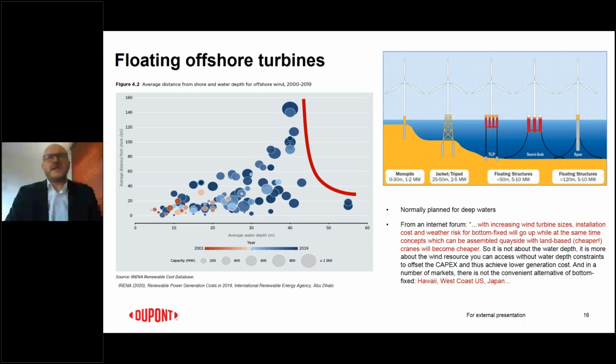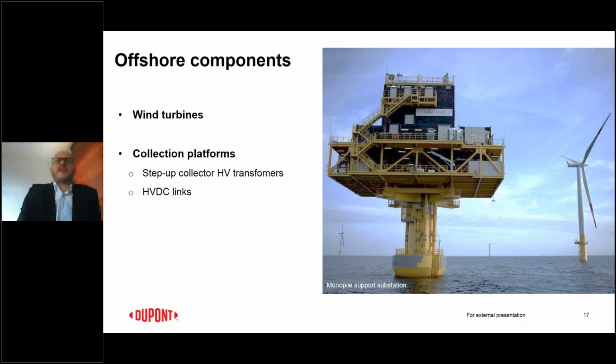And then, further staying with the offshore industry, definitely the wind turbine and the step-up wind turbine transformer are not the only components. The collector transformer is another important part. And of course, collector transformers also exist in onshore installations. They may not be so critical. There is probably not much focus on special developments for collector transformers for onshore wind farms. But in case of offshore, definitely this is a very critical piece of equipment.